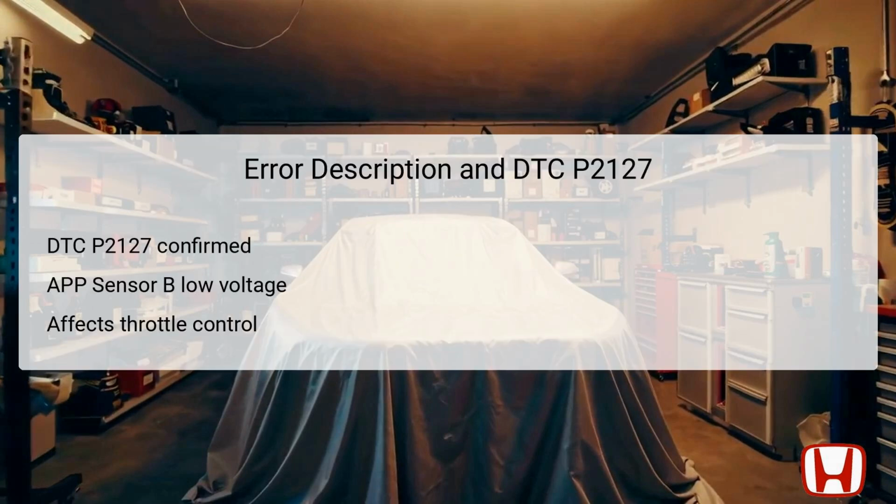The DTC P2127 has been confirmed and indicates that the APP sensor B is experiencing low voltage, which can disrupt the vehicle's throttle control. This low voltage condition often indicates a potential issue either with the sensor itself, wiring that leads to the sensor, or the PCM's ability to interpret signals correctly.